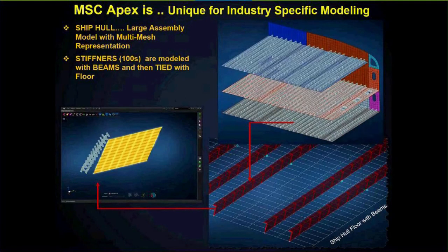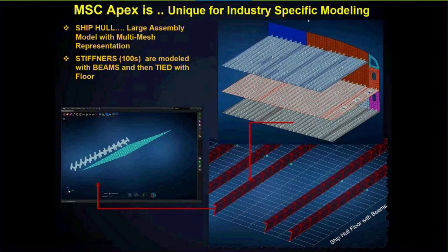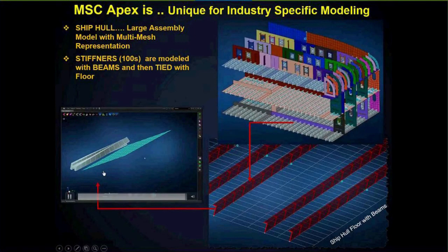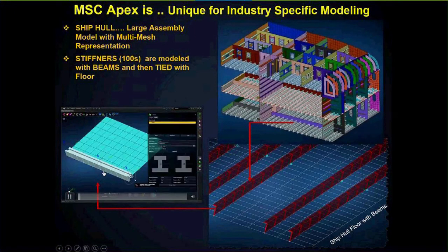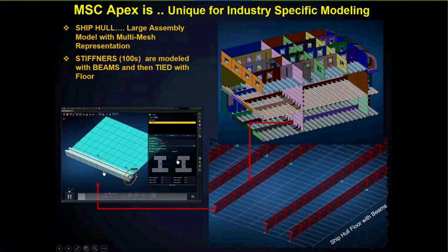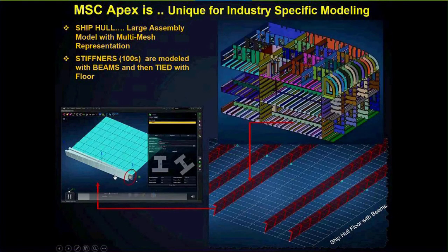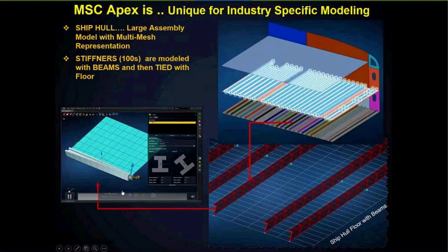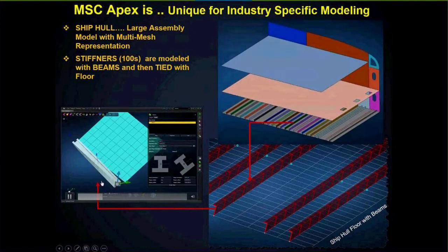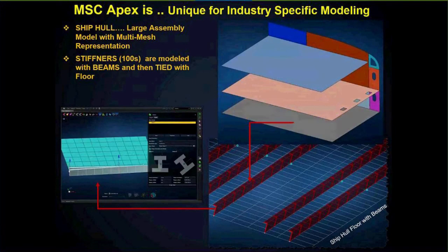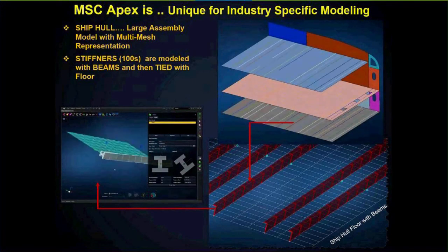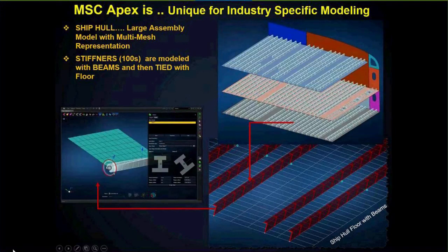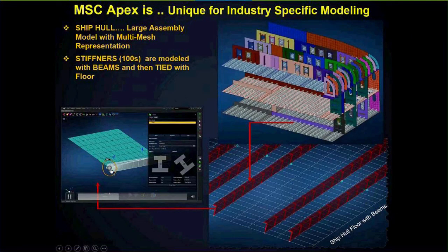Even if you would like to model this as a beam element, we do have a tool called creation of beams, a very exotic tool called shape and span. That means you can create a shape inside the tool and assign that one to a span. Then graphically you can visualize whether the orientation of this beam is proper or not. Then you can modify the orientation of the beam and even the offsets.